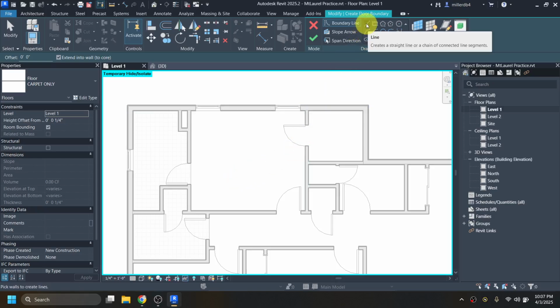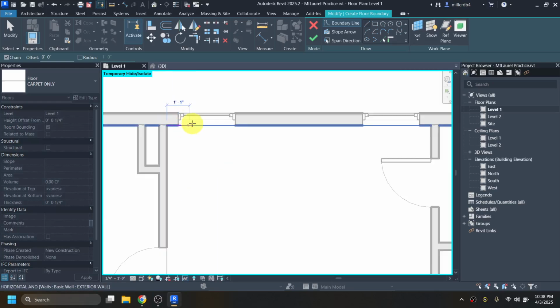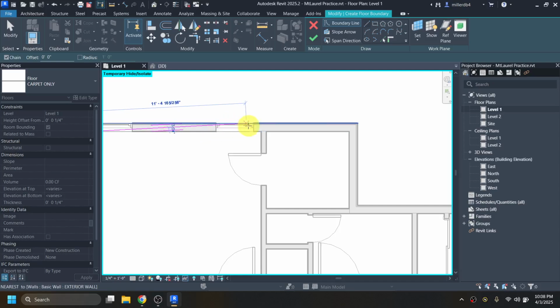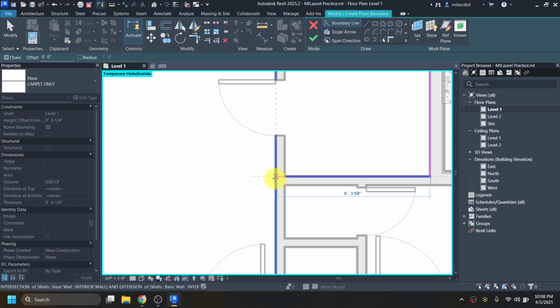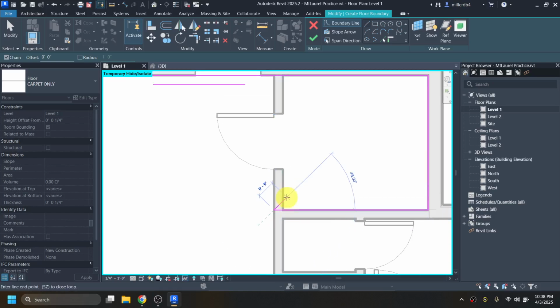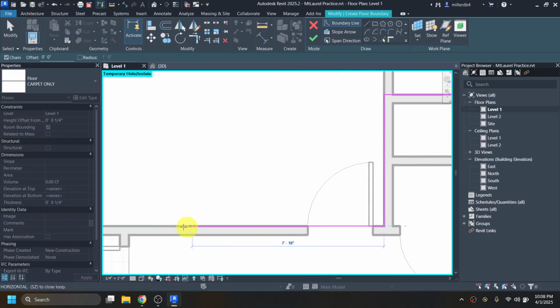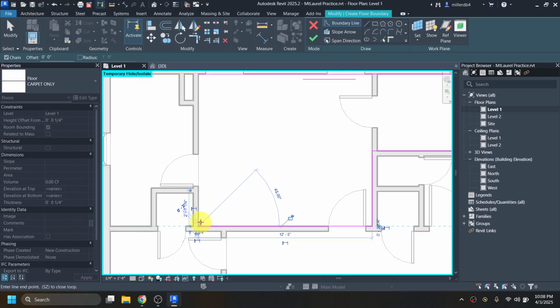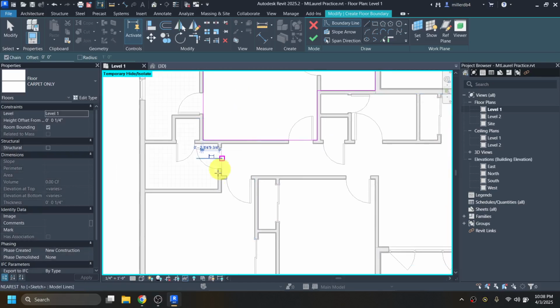And again, I'm going to use the draw line tool to draw in these floors and just trace around my interior. But since I also want this closet to have the same material, I could just skip over like this. So while we wouldn't actually want to put carpeting underneath that stud, we can just pretend it's in there. It's not going to mess up our takeoff that much.